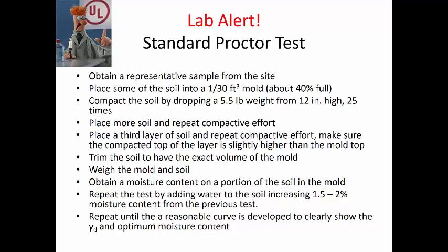Once that's completed, then the soil is typically reduced. Additional soil of the same type is obtained, and more moisture is added to it, but usually about a 1.5% to 2% increase in moisture content.